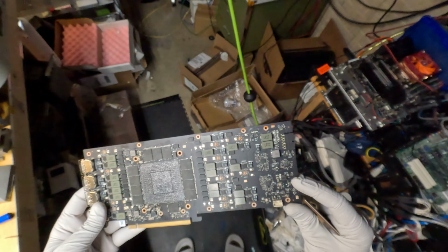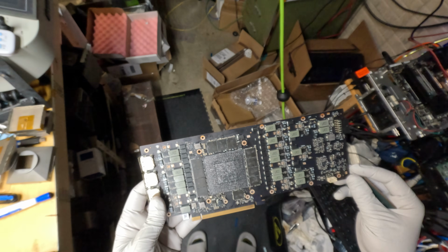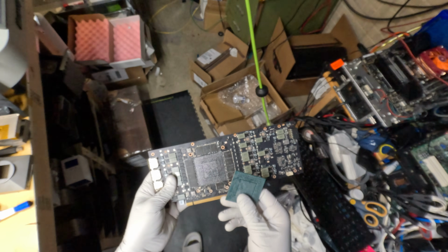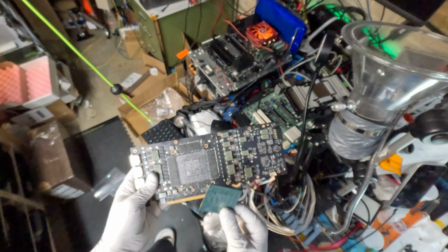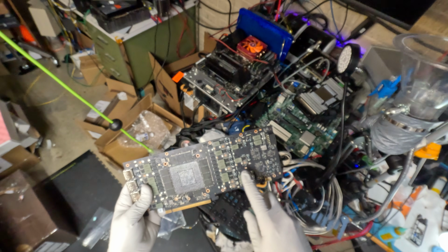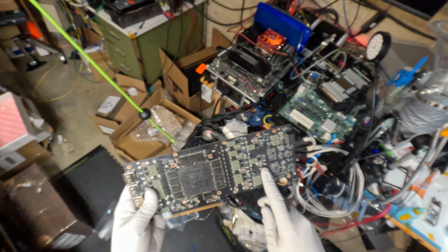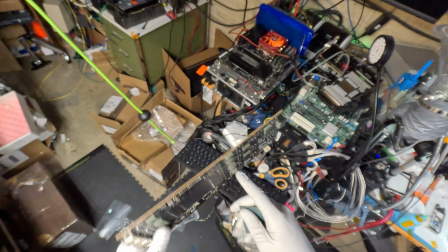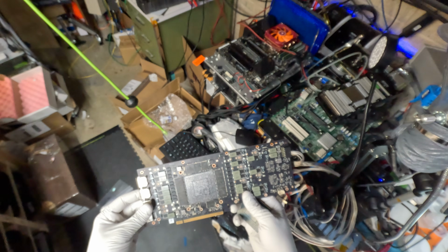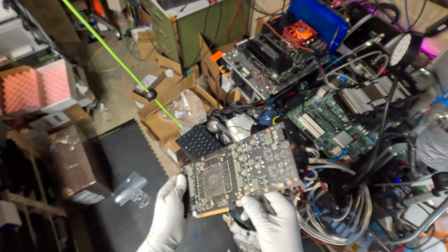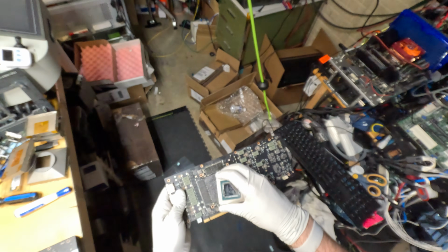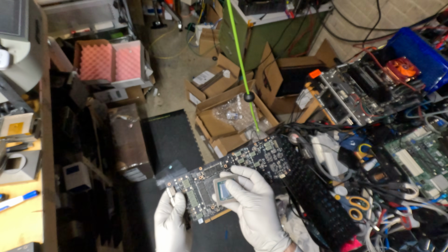I'm thinking another thing that could be causing problems is related to the circuit board used. I've done over 150 of these upgrades, and yet I have not seen a circuit board failure causing any issues. But this is a generation, I believe it's 1 or 2, I think it's 1 PCB, and there's a chance that something on the memory MOSFET side is crashing out whenever it goes over a certain power threshold. But I don't know why we want to see that on Vulkan memtest. So we're just gonna attach back on the core.